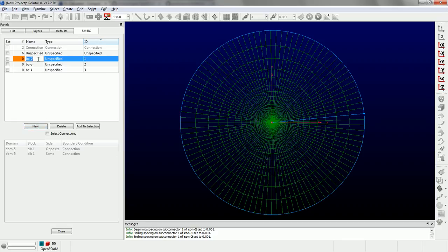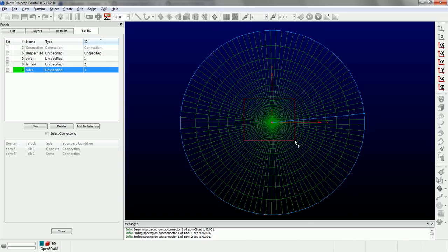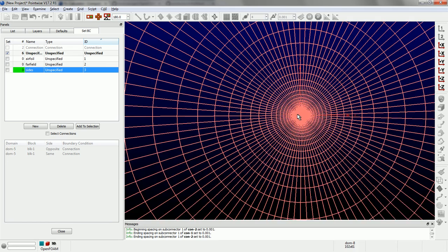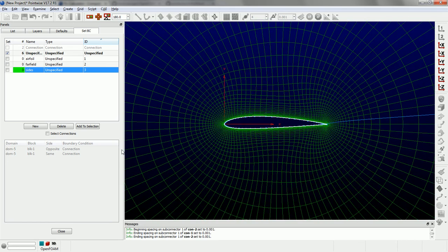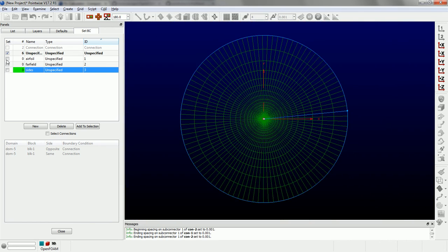So we'll create 3. The first one called airfoil. The next one called far field. And the last one called sides. Okay, so I'm going to just select those. I'm going to hold down the shift key and do an inclusive selection, and that'll just make sure. It's really hard to see, but if you zoom in there, I've selected just the airfoil surfaces. Okay, zoom back out. So I'm going to drop those into that airfoil boundary condition. And that's of type wall.